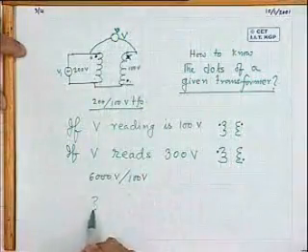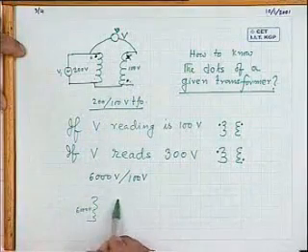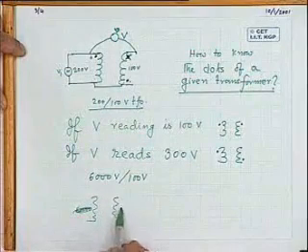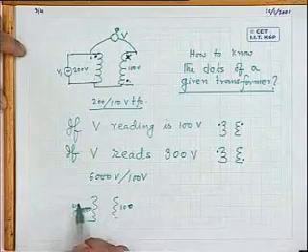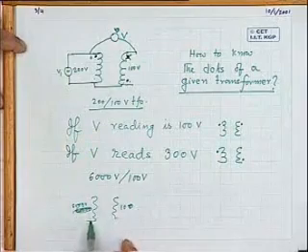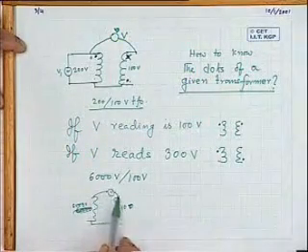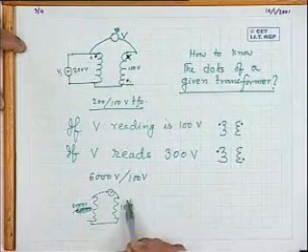Okay. I connect the transformer like this. So I will apply, say, 100 volt in the lab on this side. 6000 volt will be induced here. And if you connect like this, what will be the possible readings of the voltmeter?